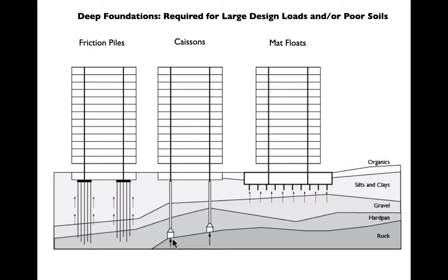And this acts basically like a spread footing at depth. So that can be maybe 80 or 100 feet down below the surface if we have a lot of poor soil, as we would in Chicago or New Orleans or a lot of coastal cities. Once that is all drilled, concrete gets poured along with usually a rebar cage, and we get this very, very long, skinny column that then can support the building structure from the lowest level on up.